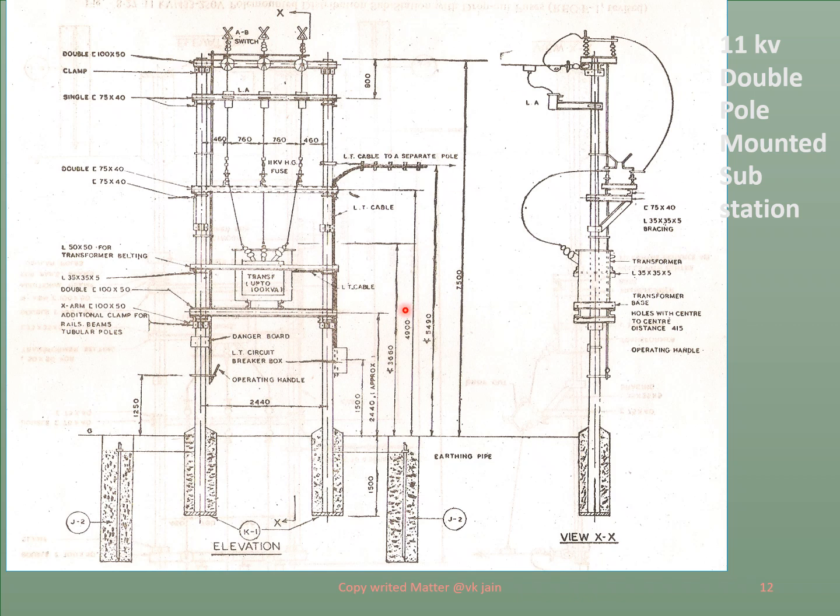Friends, in previous diagrams, I have mentioned outdoor pole mounted, double pole mounted substation. So this is the double pole system, one pole and second pole, and these are their foundations. And here you can see this is the end view, and this is the elevational view.